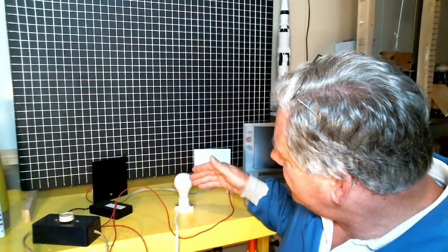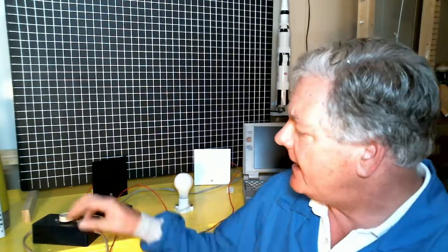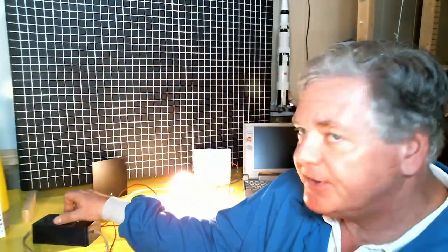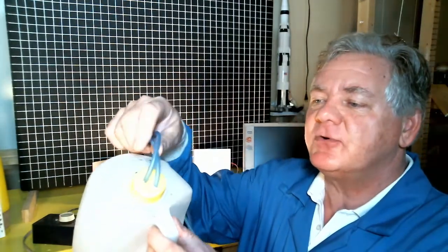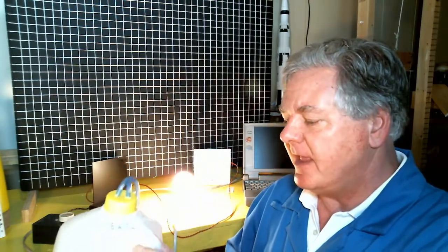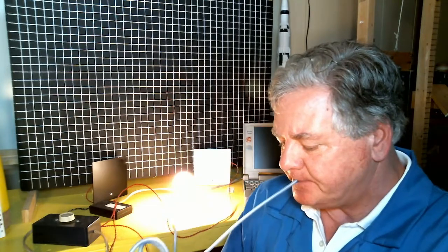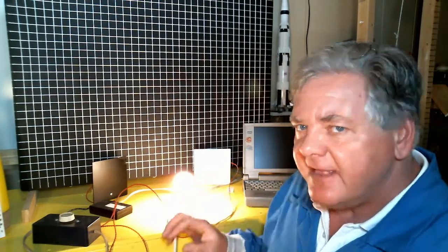Here's my simple experimental setup. I have an incandescent light bulb, which you know is the older light bulbs, and they generate a lot of heat when they produce light. I can turn on that light bulb and start producing heat. I've also got a gallon jug here that I put two rubber hoses through holes in the cap. I'm going to fill this jug with fog from a fog machine. If I blow into the container, I can get a nice stream of fog to come out at low velocity, and I can apply it around the light bulb and see if we can set up convection currents around the light bulb due to the heat that's generated.